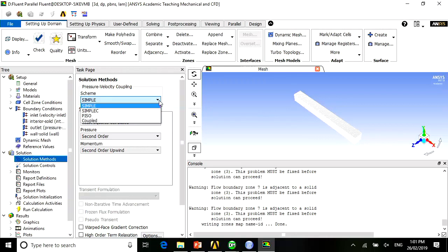You know, if I give you a history, basically, it involves the calculation of 2 pressure corrections. That means that SIMPLE uses 1 pressure correction to calculate the solution. Once you get the solution, it goes to another pressure correction to update the mass conservation. So it should be more effective in the sense that you should get faster convergence towards your mass conservation at the end of the day. But that's what PISO means, okay? So PISO was developed by a professor from Imperial College, right? So he is the one who developed that, which proves to be quite effective. That's why PISO is there, right?